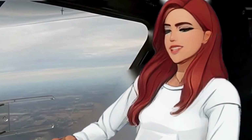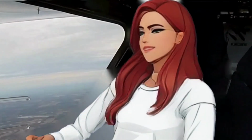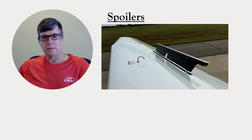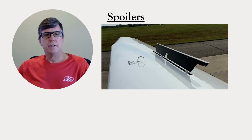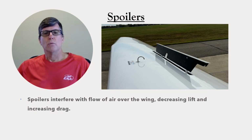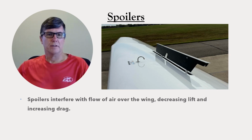There are a couple other types of secondary aerodynamic controls that we don't have in this aircraft. Spoilers are controls which extend above and sometimes below the wing. Sometimes it's a plate like the one shown here, other times they're hinged. They increase the drag and they reduce the lift. So you may wonder why you would want to do that. Well, on aircraft with very little parasitic drag, spoilers are useful for controlling a descent.